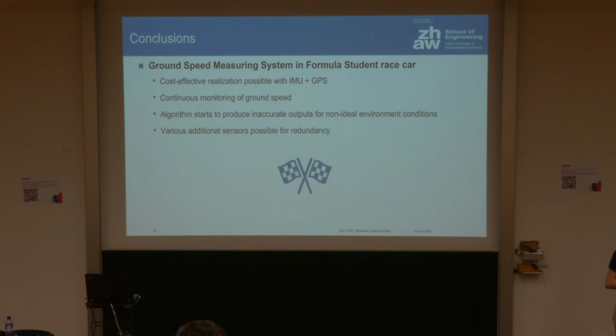Yes? Another question. You showed us that you are using the signals from the IMU and GPS to calculate the velocity. How does this computed velocity compare to the velocity that we would derive from the IMU alone and from the GPS alone? How much does adding these two pieces of information bring you? The cool thing is that the GPS usually has a slower frequency of delivering data to us, and we can add more points to this signal by using the IMU.